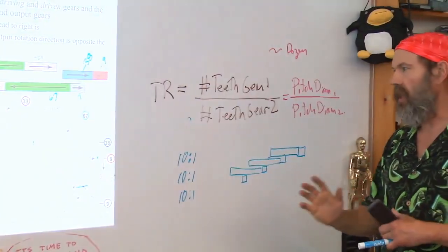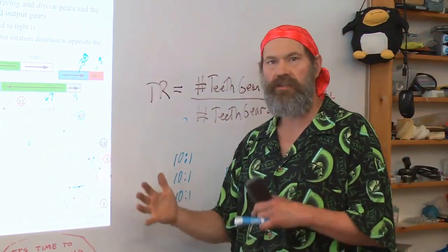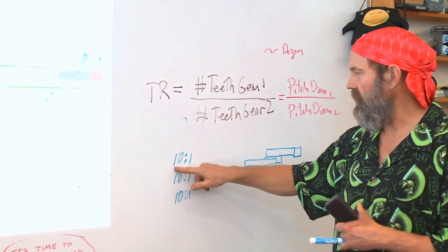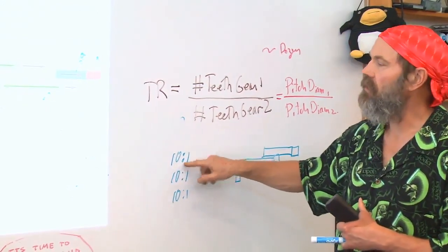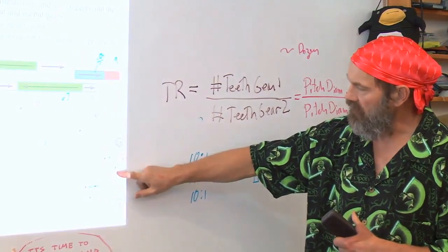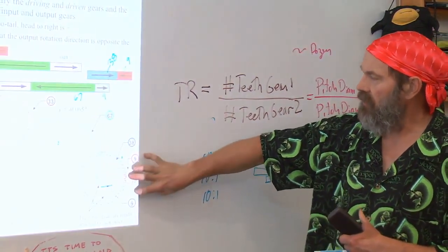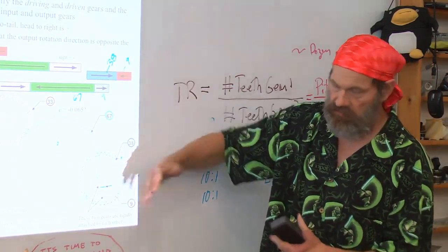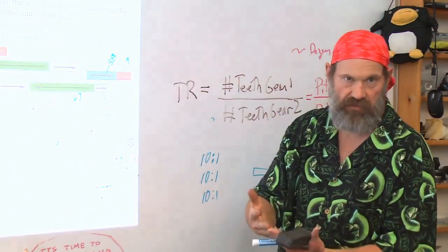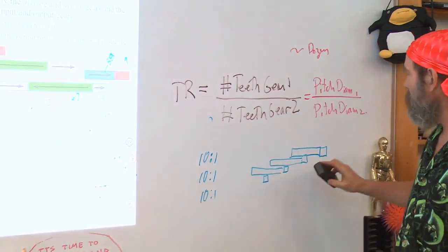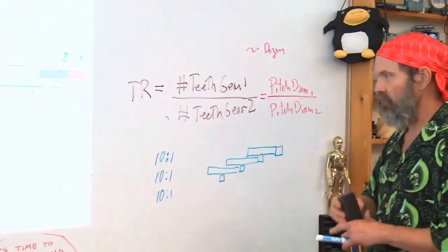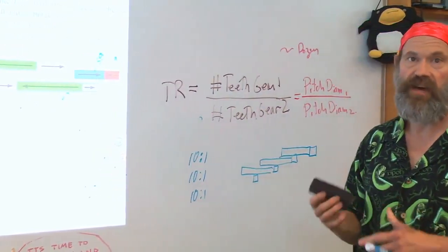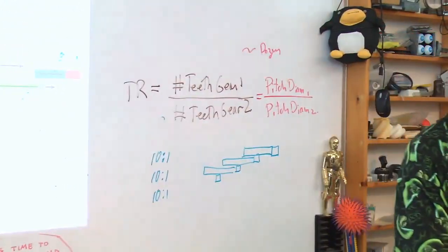Remember though, every time gears engage and disengage, there is a net efficiency loss. And the higher this ratio is in a stage, the lower the efficiency tends to be, due to the number of teeth and the way they engage getting harder and harder to do efficiently, due to the nature of the geometry of the involute when you have these extreme differences in sizes. But they're still fairly efficient. You can have upwards of 90% efficiency per stage and higher in some cases, even 95% with really well-designed helical gears.